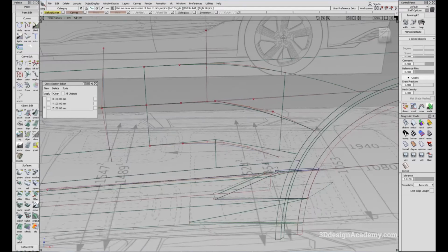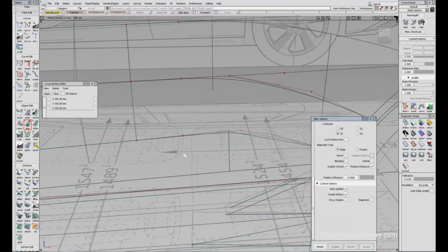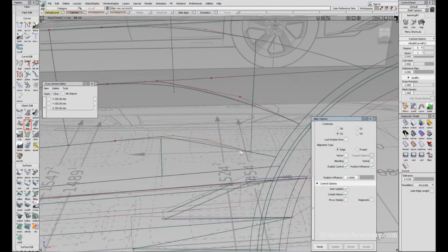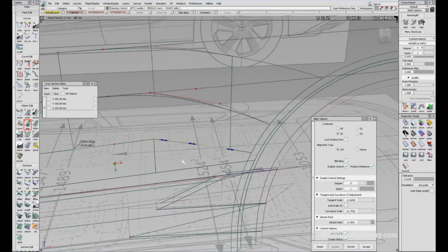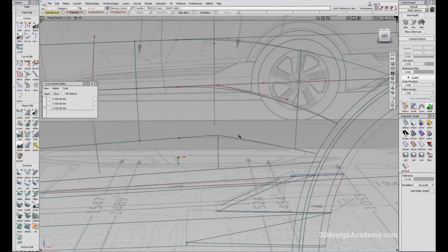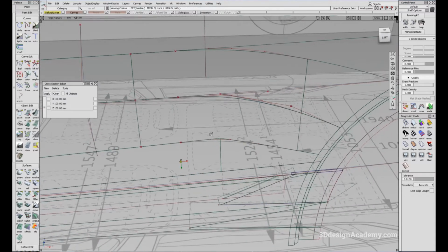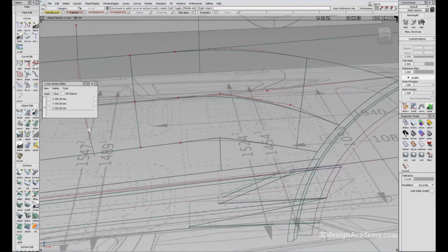So I'm just going to delete that curve, and I'm going to use the stretch tool just to connect the end. And what I'm going to do next, I'm just going to use align over here, G2, and align here, G2. So now we have a G2 continuous curve that is also harmonious, and the CV structures are similar between the top one and the one at the top.